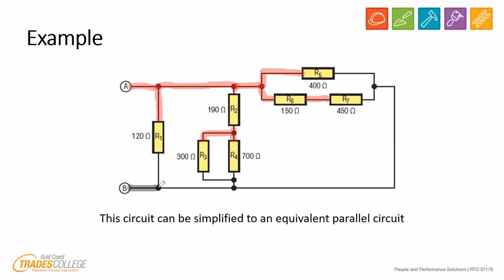Obviously, I'll draw in the black. And as you can see, R1 is nice and easy. There's nothing in its way. That's why we don't need to do anything to it. I'll have a look at these two. So these two are connected in parallel at the bottom. These two would be great if they didn't have R2 in series with them. And then same thing over here. They've just drawn this to try and confuse you a little bit. The way that looks there, as you can see, the red is coming in and going out. It's identical to it being vertical. They've just drawn it that way.